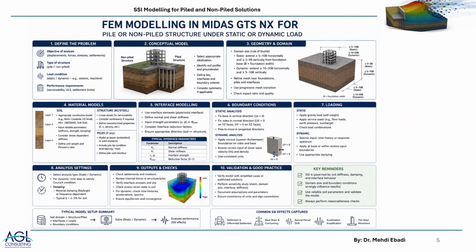And on the other side, if you have a model that your limits are too wide, that's adding unnecessary elements to your model, which you'll pay for by spending more time and energy. And unfortunately, less accuracy in general, because your elements cannot be as small as you need. Otherwise, the calculation time will exponentially increase. So that needs to be in balance.